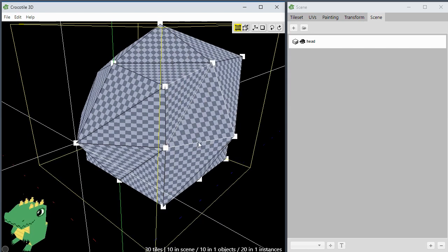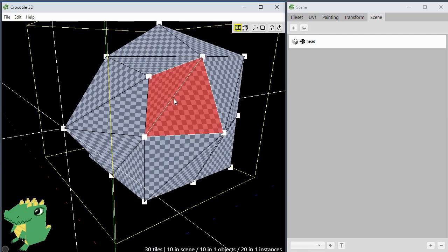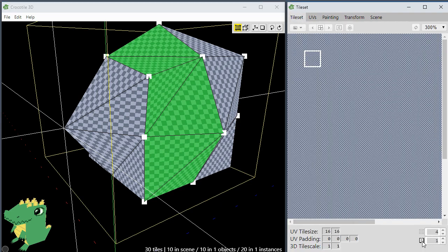So we could go in and, if you want, you could select some tiles like this and then hit the middle mouse button and it'll put it into active edit mode, and it shows this line here to split tiles, so you could split the tiles into 2 tiles, and there's a setting down here, the tile splitting setting, and if you adjust this it'll change where you could split it, like how many pixels at a time basically, or along the space of it.